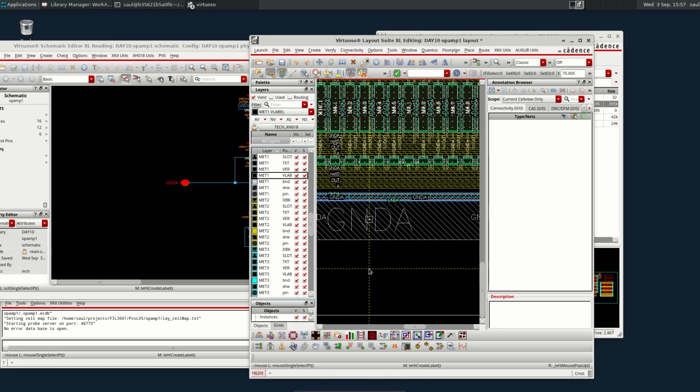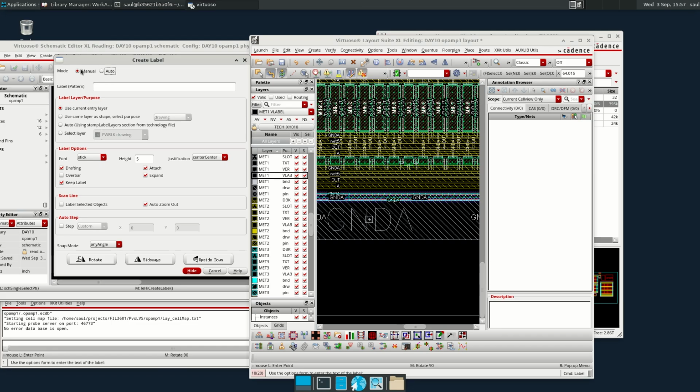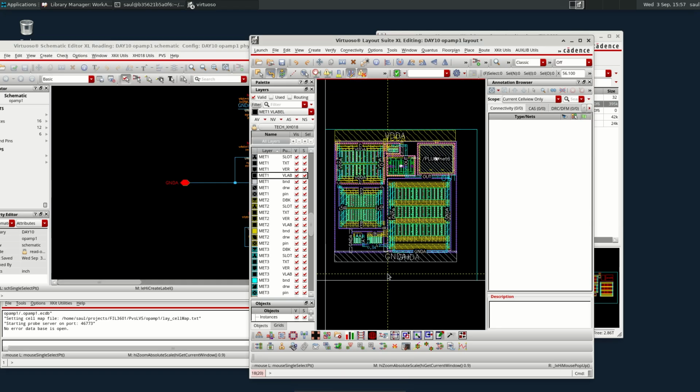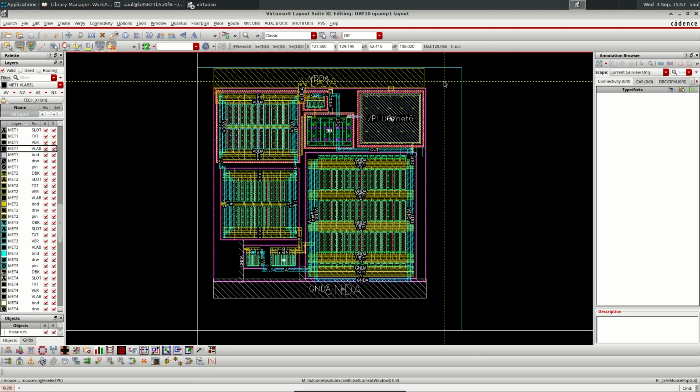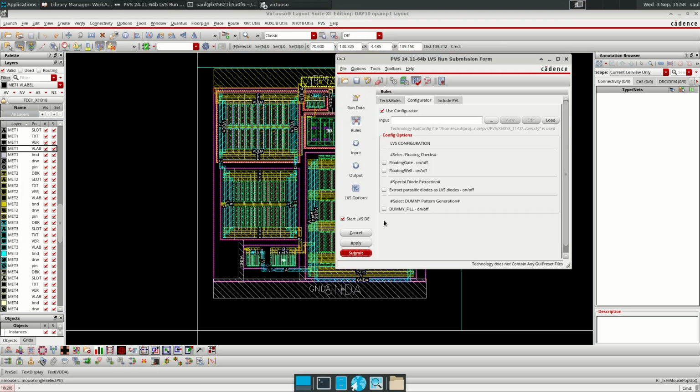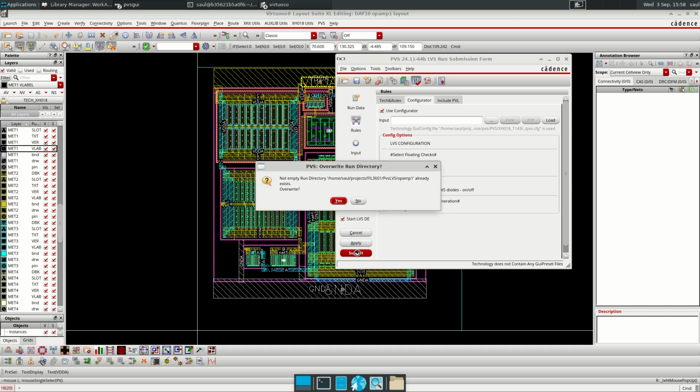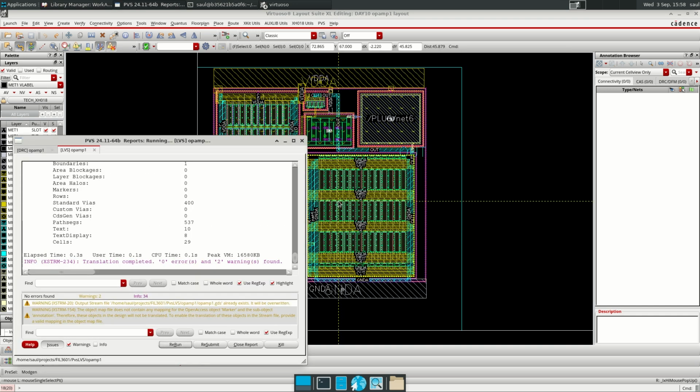Now think that I can also add manually. I can put a name and then add it exactly on the top, but yeah, if I have the automatic, I prefer to do the automatic. And that should make it. Let's see if now we run the LVS, and then we pass LVS, run LVS, make, yes.